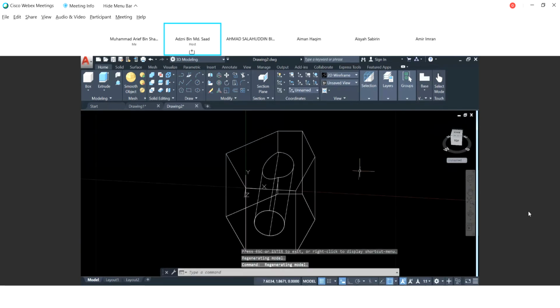So if you want to change one plane to become an XY plane so that you can construct a geometric drawing, first of all, you need to choose the plane that you want to construct on. Okay, if I want to construct on this top plane, I go directly to this cube on your top right hand side.